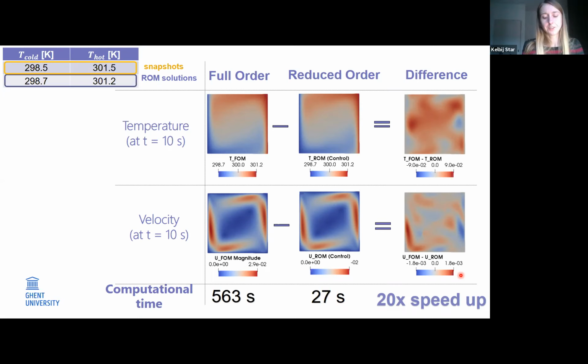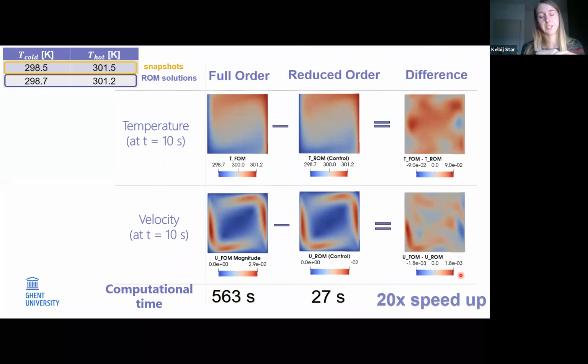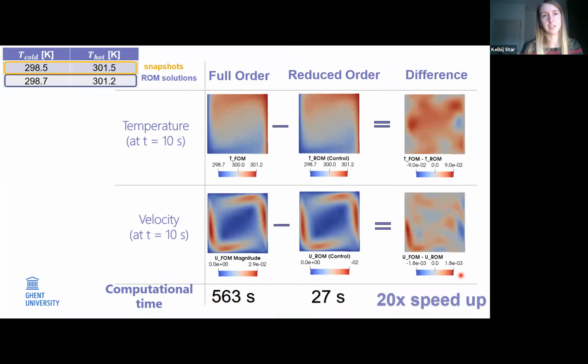Yes. So what you often see happening, for example, at the beginning of simulations that start from a zero flow field, is that during the beginning of your time interval the flow is changing the fastest compared to later on in your simulation. And what you then need is to collect more snapshots in that time period. So if you really want to set up a reduced order model that is valid for a flow that is first in a laminar regime, then in a transition regime, and then also becomes turbulent throughout the whole time interval, your reduced order model won't be accurate for all of the regimes.